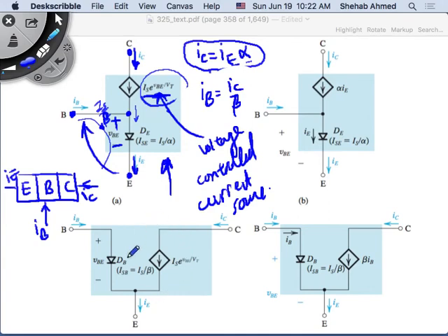What does this look like? Does it satisfy our equations? Right, these are the equations that we have. So we have current flowing through my base, forward biasing the base to emitter junction, right? So I have VBE here. That looks like a diode, and that current we said is going to be added to collector currents, and they will both create the emitter current. And this collector current is the same as this, IS e to the VBE over VT.